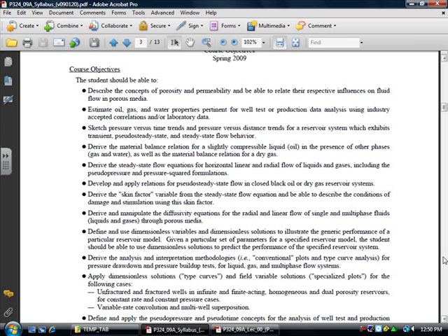Now, what if I tell you you can paint with some magic paint that will actually make the pressure drop be negative? In other words, when the pressure gets to the wellbore, physically, it will go up. Well, that's impossible. But mathematically, the skin factor doesn't care whether it's positive or negative. So you can use the skin factor to represent damage in a very systematic and sort of mentally consistent way.